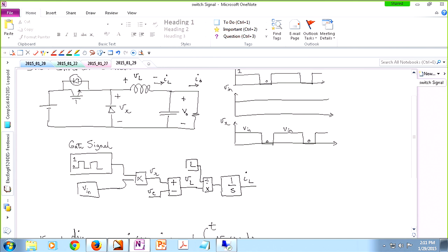The difference between these two will be the capacitor current. So again, this time I'm closing the loop above. So if I happen to have Iout, and I will make it later, if I subtract Iout from IL, that gives me IC, the capacitor current.